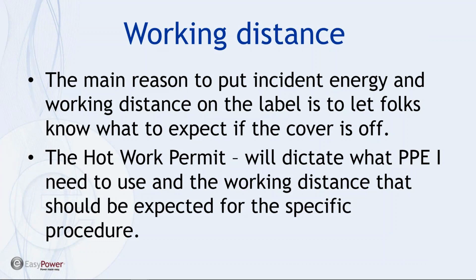Now, the working distance, the main reason to put incident energy and working distance on the label is to let qualified people know what to expect if the cover's off. Now, that doesn't tell me anything about the hot work. That doesn't tell me anything about the actual requirements of the maintenance. All that falls into the purview of the hot work permit.